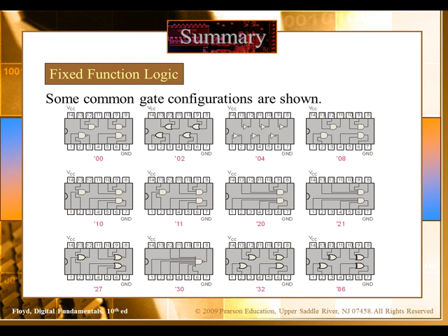So which one do you want to use? You need just 1, let's say. You can use any of those. There is no rule that you have to use the first one. You can use any of those, but make sure you use the right input and output. You can either use pins 5 and 6, because pin 5 is the input and pin 6 is the output, or maybe you can use this pair. Whichever one you want, you can use that.